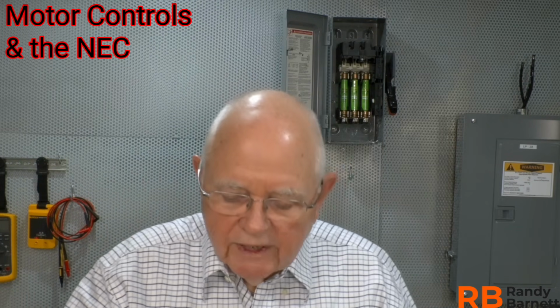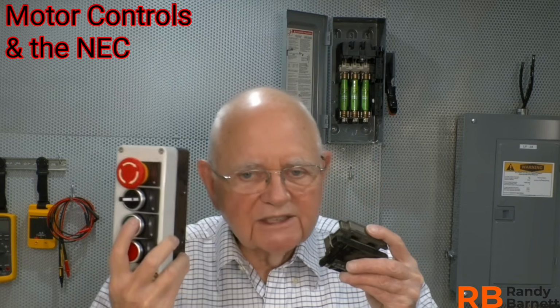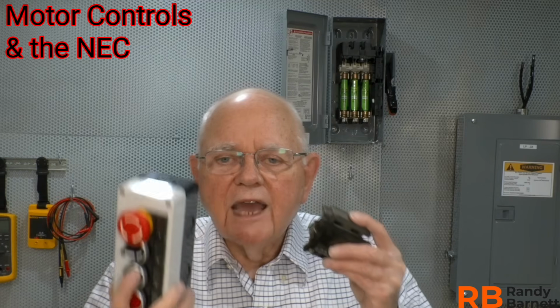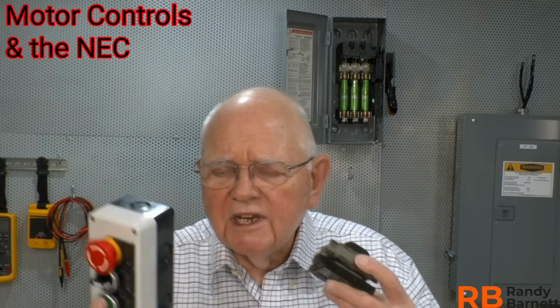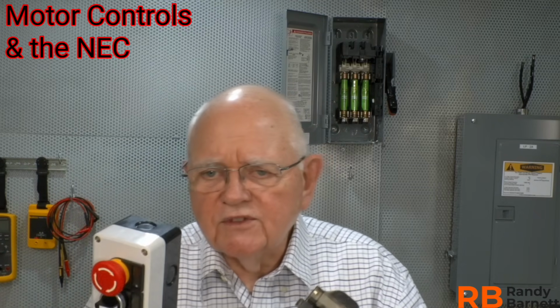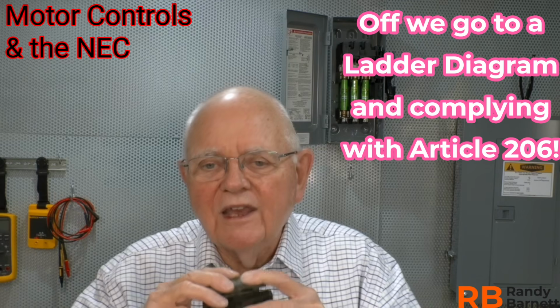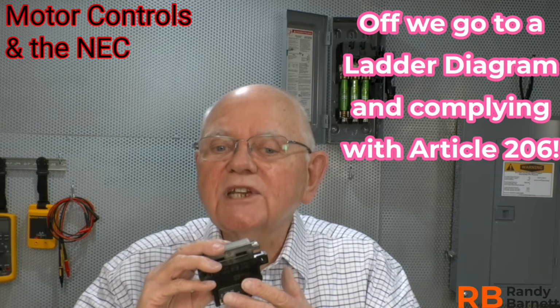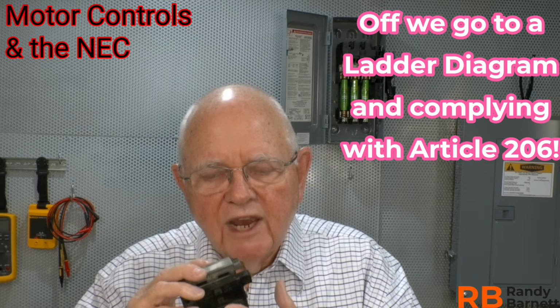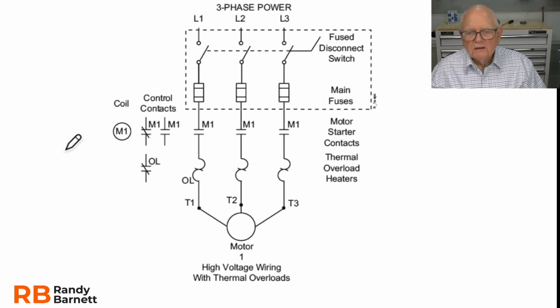Let's take a look at Article 206 in the NEC, because that's most likely what we're going to deal with, and how we're going to determine what size conductors we need based on what the power supply is to this control circuit. And no, I don't need number 10 or 12 wire going to this coil. Let's take a look in Article 206, go through a schematic diagram, walk through it, and see how Article 206 applies. So let's begin by taking a look at our main power circuit that we've been talking about.